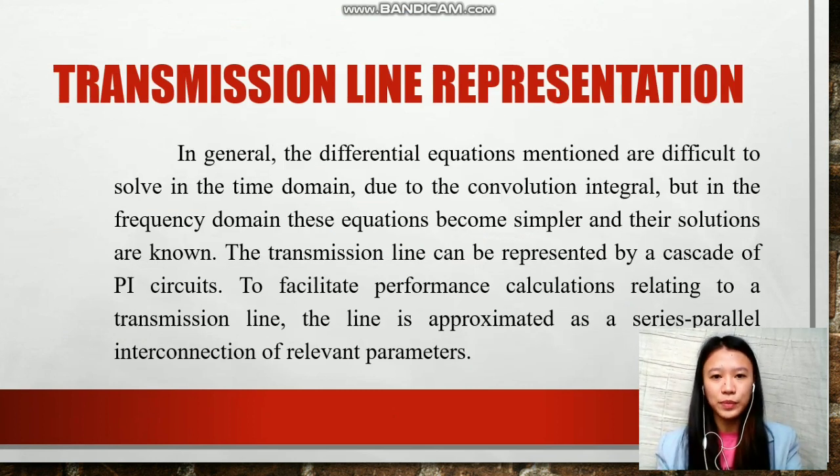Now that we're familiar with the transmission line, let us proceed to the background of the transmission line, which is the transmission line representation. In general, the differential equations mentioned are difficult to solve in the time domain due to the convolution integral. But in the frequency domain, these equations become simpler and their solutions are known, which means the transmission line can be represented by a cascade of PI circuits to facilitate performance calculations, in which the transmission line is approximated as a series-parallel interconnection of relevant parameters.